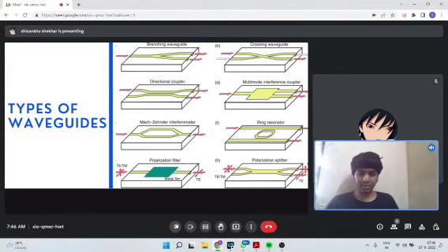Fiber optics is one of the cases, but there are multiple waveguides through which you want your energy of light to pass. An example is a branching waveguide, wherein you have a light passing and after that there's a split, so you split the incoming light into two branches. After that, there is a crossing waveguide wherein you want the energy of two to combine at one point and diverge back again from that intersection point. Then directional couplers are when two lines come close, wherein they don't exactly meet, but there is some sort of energy exchange through wave optics. So that is about that.